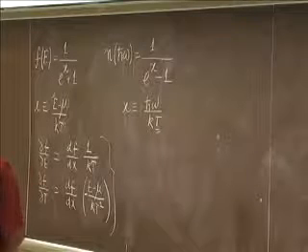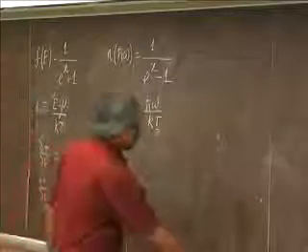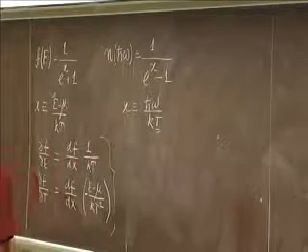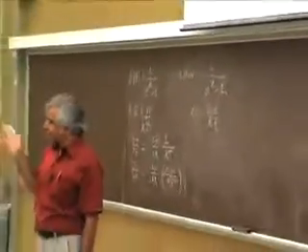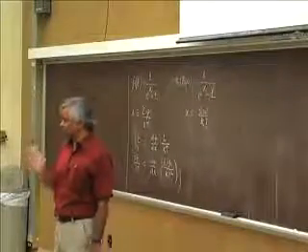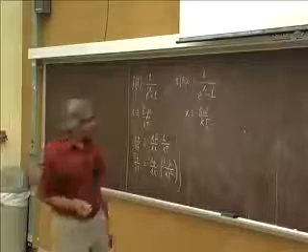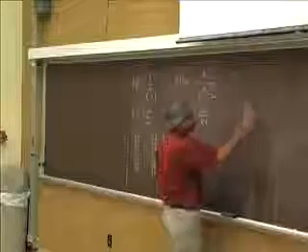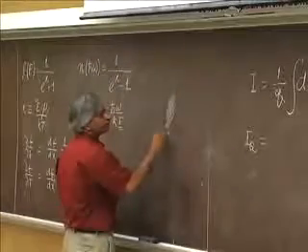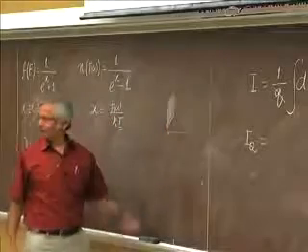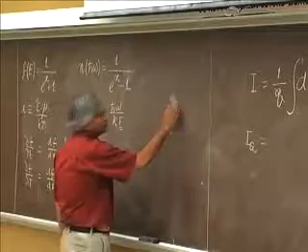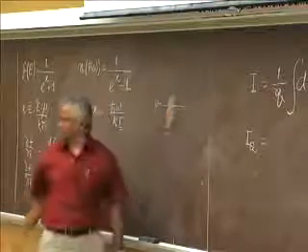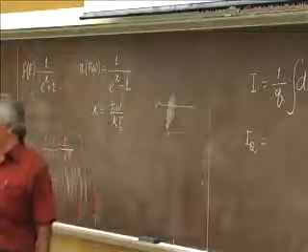this is the point, though. As a general principle, what drives flow is not so much the density difference as this electrochemical potential difference. Sometimes I ask this question: if you had a material which had a very high density of states here and a very low density of states here, then when they come to equilibrium, the mu will be the same across. And so there will be lots of electrons here, very few electrons there. It's not like the number of electrons is getting equalized.